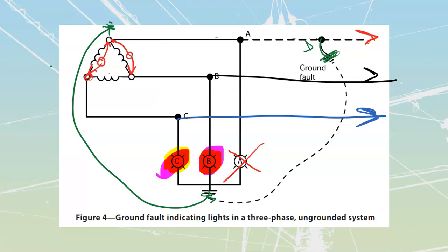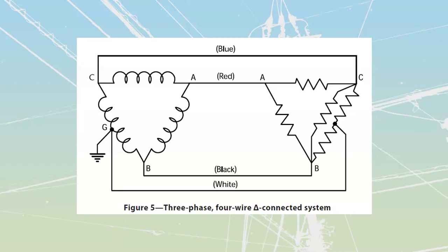We also have another specialty system we're going to take a look at. This is going to be called my 3-phase 4-wire delta system, and it is an oddity. Chances are most of you will never run into it in the field. These are not put in as brand new services. These are usually going to be put in, dropped off someplace where I've got a delta system and primarily motor loads, because delta is really good for motors.